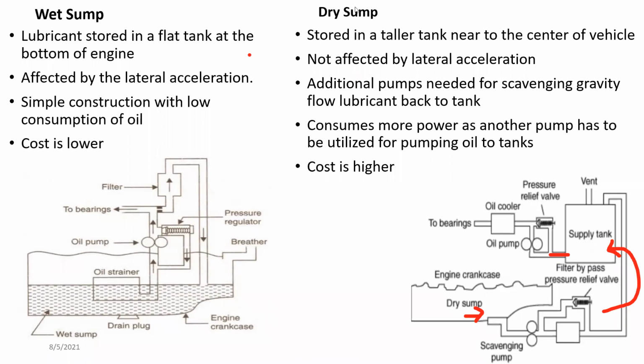It does not matter how much lateral acceleration is felt by the vehicle, because the volume of the separate tank that holds engine oil can be increased, whereas in the wet sump it is very limited. So it's not affected by the lateral acceleration.